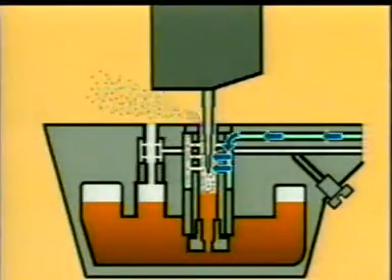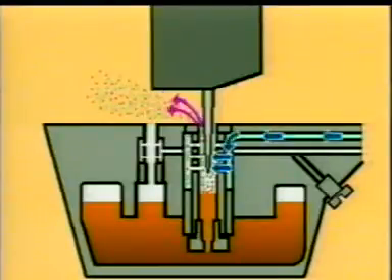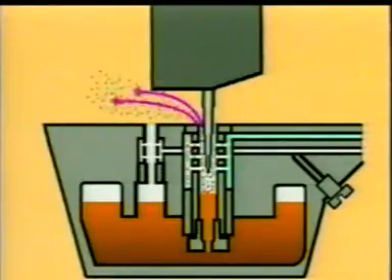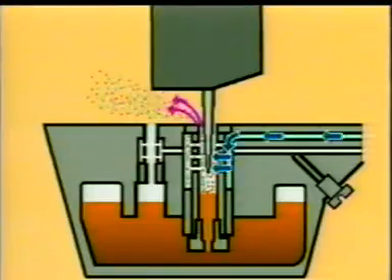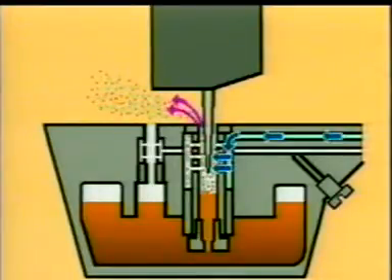Using this principle, we made several small holes in the side of the pilot jet, in the pilot system, and in the needle jet, in the main system. The air and fuel coming from the pilot air jet and the main air jet are mixed and bubbles are produced. This makes it easier to turn the mixture into a spray as it passes through the venturi.